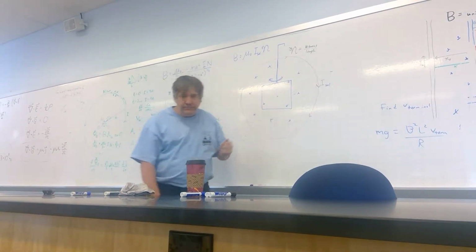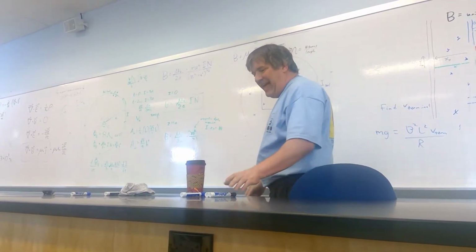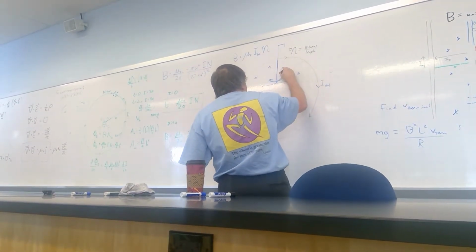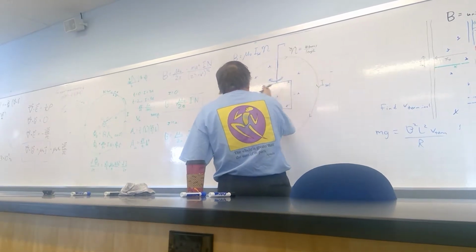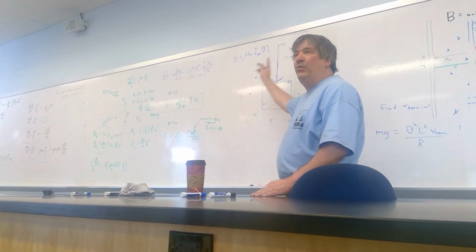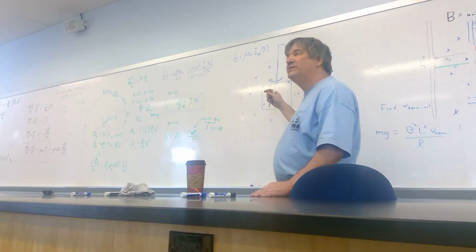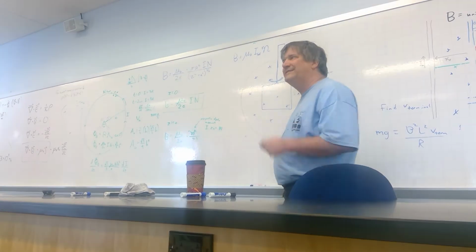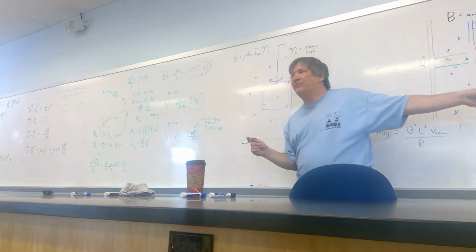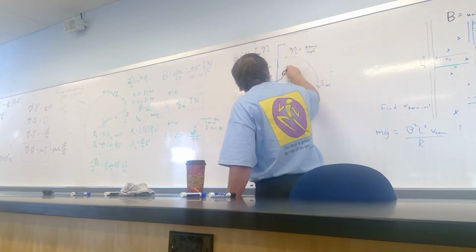Okay. So I've got my solenoid, I've got my uniform B field, I've got my square of side length S, and I have got somebody turning this crank up here at a rate of, well, if I want to generate power that's compatible with the power that I take off the grid, what rate do I want to spin that square at? "60 cycles per second." Yeah, the AC power that we get from wall outlets oscillates at 60 cycles per second. If I wanted to match that, because maybe I'm planning on feeding some device that's meant to run on 60 cycle per second power, then I want this thing to be spinning at 60 cycles per second.